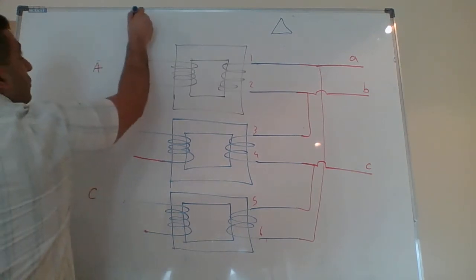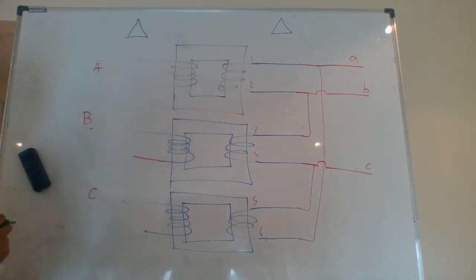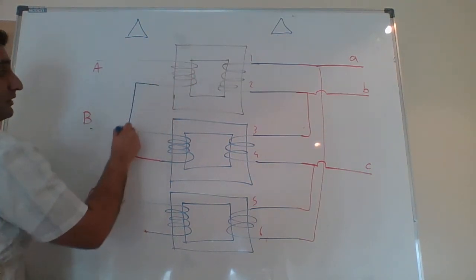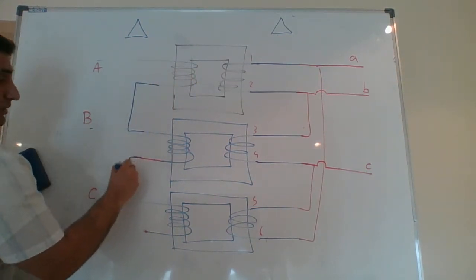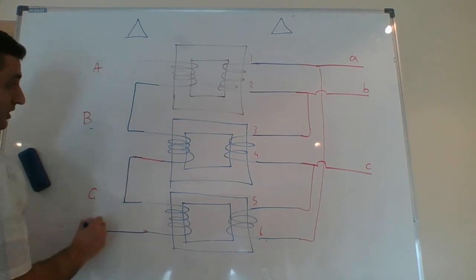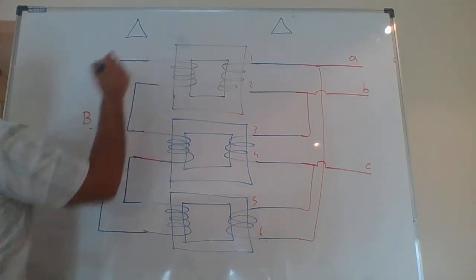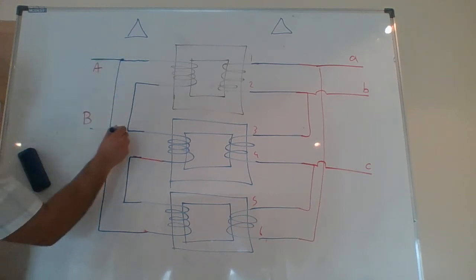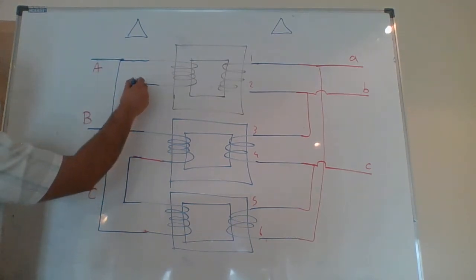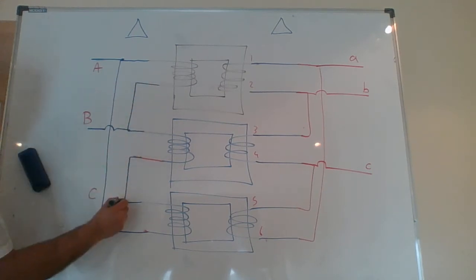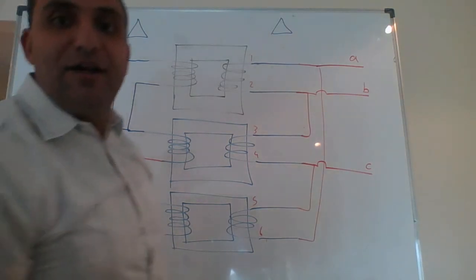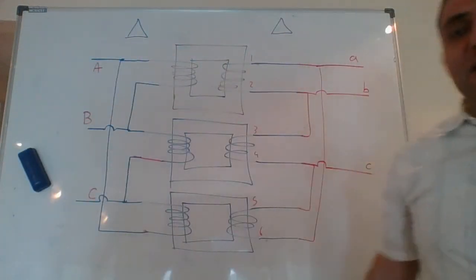And I am going to connect this as a delta delta. So what I do is this one will be connected to this one. This one will be connected to this. This will go all the way down to here. This is A, will remain. This will become B. Remember, this is the same node, and this will become C. That's what I have. Delta delta connection.